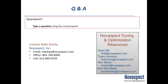Another question here was, what software was Mike using for the simulator? I was actually using DeltaV, our Emerson DeltaV control system. It's normally something we use to control a plant. In this case, I used it for all my control, and I built my process models with function blocks. It was actually a pretty simple effort to do it. So I didn't have a control system plus a simulator. I used the control system itself to do both jobs.